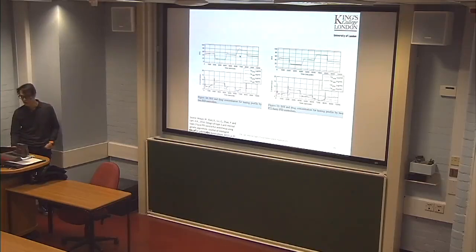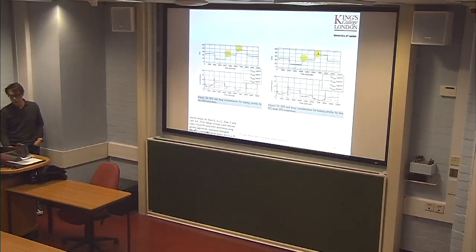Comparing these two figures, you can see that the two methods can do almost the same thing, because the blue line is within the green region. The blue line is very close to the green line right here. But focus on the overshoot. When we use the interval type 2 fuzzy controller, we are able to suppress very well the overshoot or the undershoot.